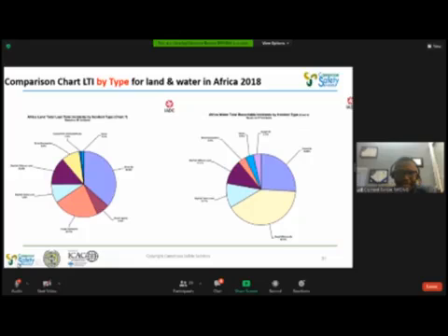Now by type, we have this lost time injury by type. We have a type where people are struck by, for example if the lifting of a tool or a basket swings, it can easily strike someone standing by. People walking on the rig floor during trip out, the pipe can swing and strike someone standing by. So we also have caught in between, especially on the main deck when the guys are walking.